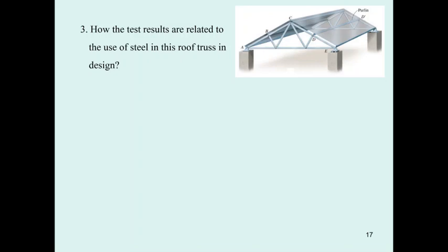As I mentioned before, the yielding stress is going to be divided by the factor of safety to be the allowable stress, and also for the deflection of the truss, you're going to use the modulus of elasticity and put it into the equation we have used to predict this truss deflection without needing to do a full scale test, which is very important.